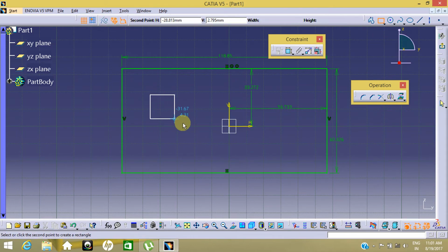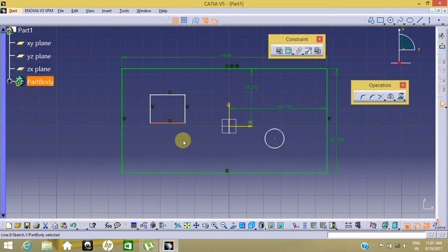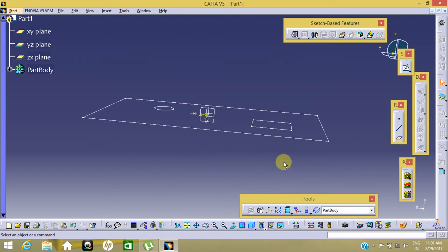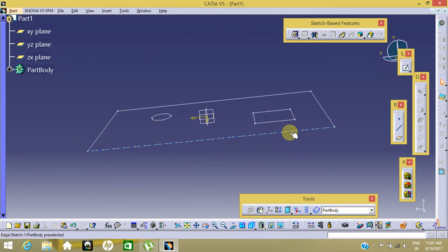So just go to the multipad that is here and click on sketch. So you will see in our dialog box it is asking for a length, for each of the three sketches. First sketch is this one, second sketch is this one, and third sketch is this one.